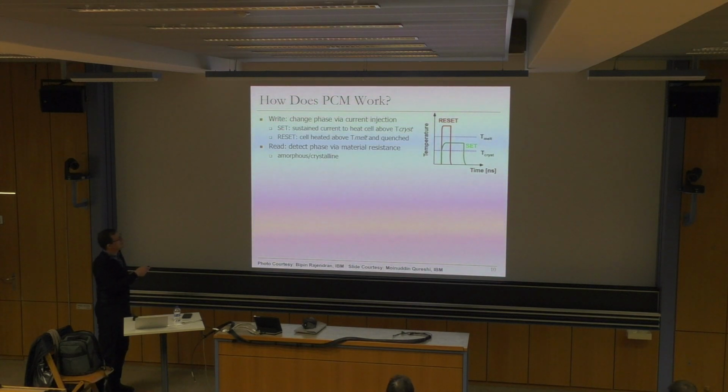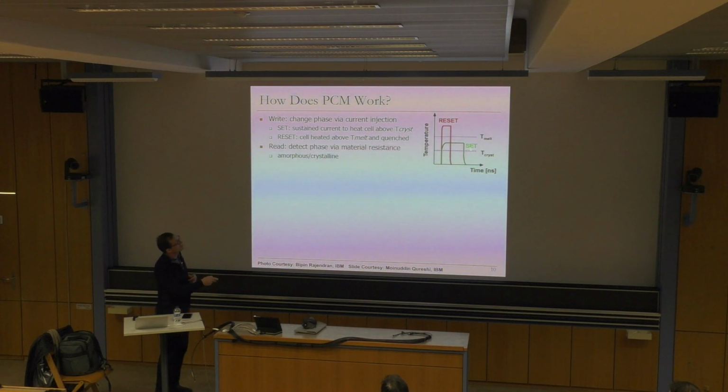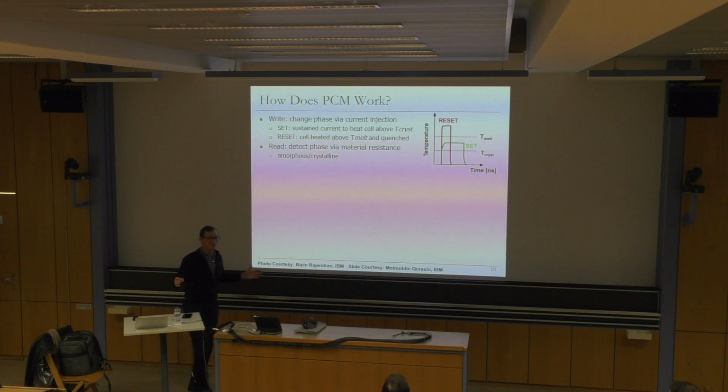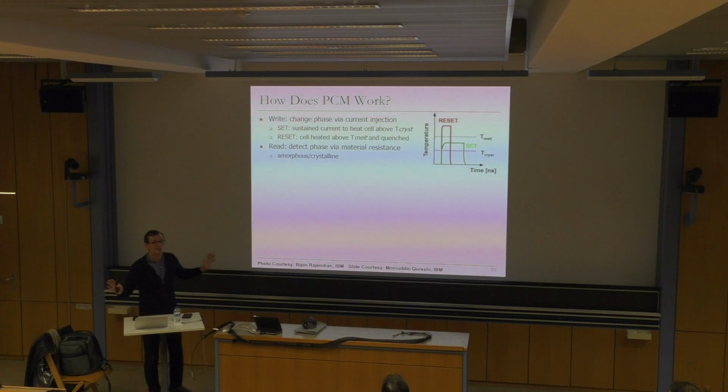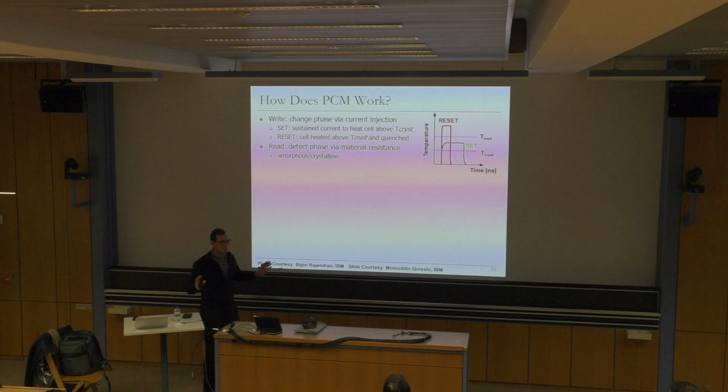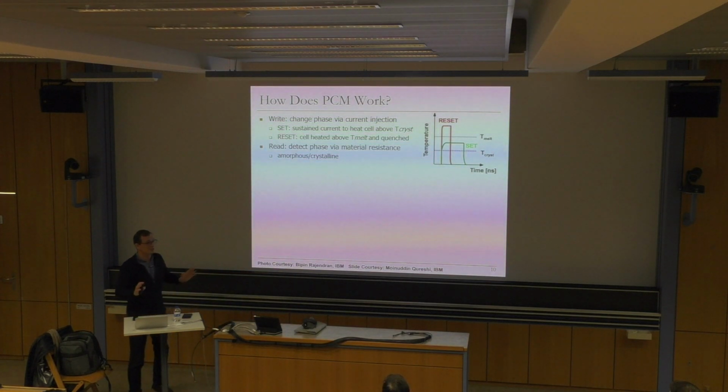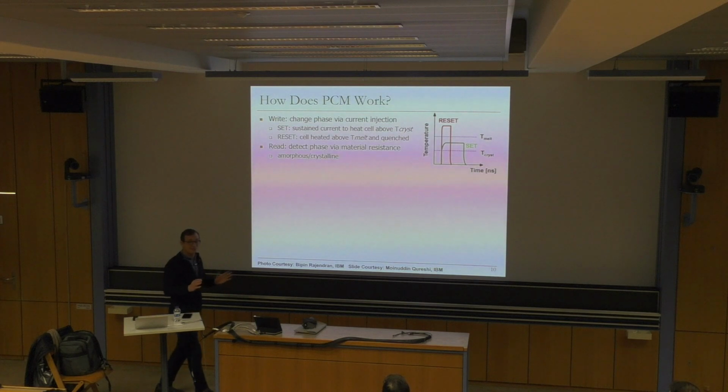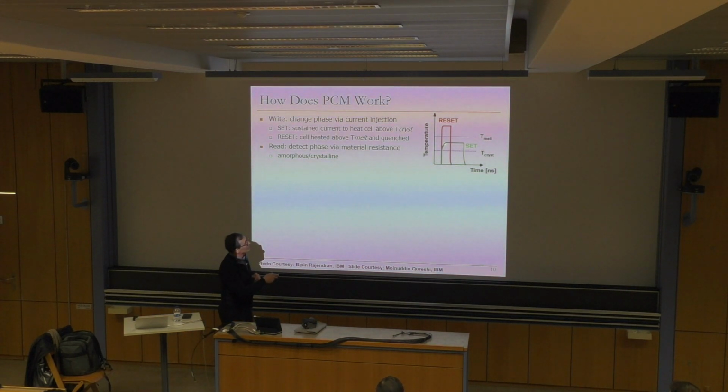For example, if you want to set the cell, you need to supply sustained current to keep the cell above some crystallization temperature. And this gives you a picture, for example. You need to essentially sustain the current for some amount of time, and that amount of time is much longer than DRAM. Let's say 10 to 12x longer. And I believe in existing 3D XPoint devices, it's even longer. I don't want to say any numbers, but there are some publications out there that claim some numbers. You can read those if you're interested in 3D XPoint. But it's much longer than DRAM, basically. That's the takeaway. And you need to sustain it for some time at high temperatures, as you can see.